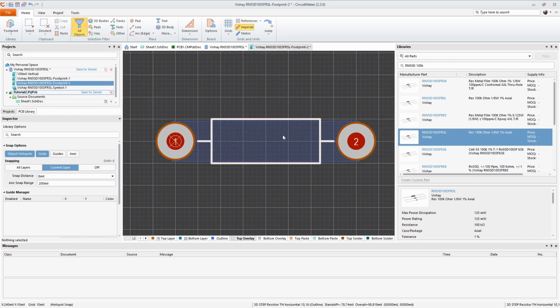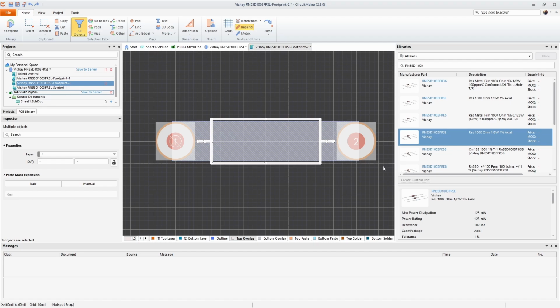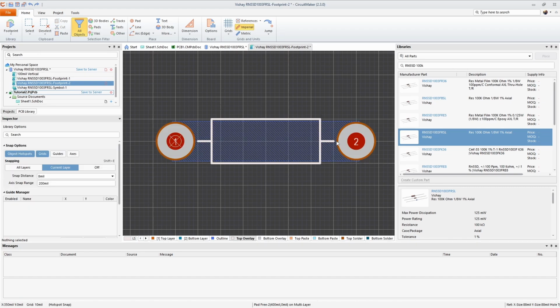This is one fairly standard way of doing the footprint for a resistor like this, and that is a complete footprint. Now, if you want to save yourself a little bit of effort whenever you go to create the next footprint, go ahead and select all of this, hit Control-C, and then you get a cursor. This cursor lets you select where your copy is going to be centered on. And the best place to center it is on pin 1. Left click on pin 1, and now we have a copy of that footprint.